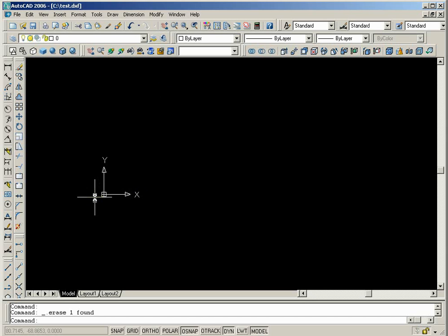What Sidewinder allows you to do is bring in a polyline from AutoCAD. That polyline can have concave and convex radii in it. It can have pulleys in it and drive stations in it and the whole take-up arrangement in it, but it needs to be a single polyline. So that sometimes takes a little bit of massaging, and the polyline can be drawn either way. Normally, you'd start at the tail and draw it all the way to the head.